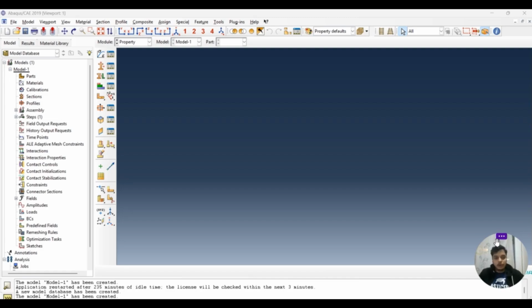Here, our main goal is to understand the constraint types, how to apply the constraints, and make sure that whenever we say contact, they are simply a subset of constraints. So constraints are something like how two bodies or two surfaces are tied together, or just constrained so that they have restricted motion. That's what we will see with an example, and also in this example, we will see some of the plastic behavior of the material, which means nonlinearity of the material.